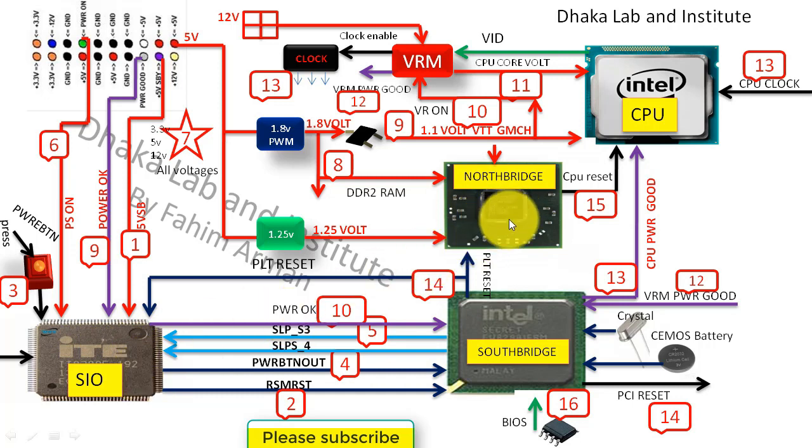And there are also many things here. If CPU reset is not confirmed, you can see that the north bridge has a problem. If you don't have CPU power good, then you can say that there is a problem on the south bridge. And if you do not have the VID signal, then you can see there is a problem in the CPU. And if the VRM chip doesn't provide VRM power good, then you can say that the VRM section has a problem.